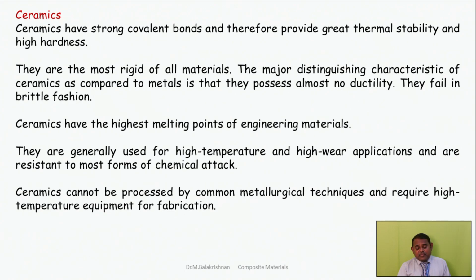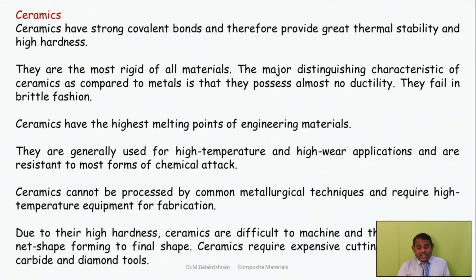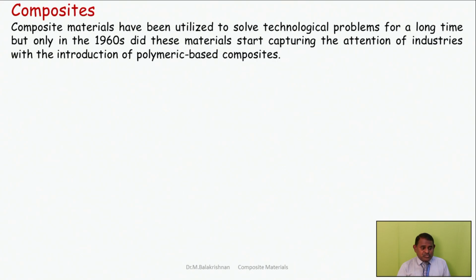And ceramics cannot be produced by common metallurgical techniques, and they require high temperature equipment for fabrication. Due to their high hardness, ceramics are difficult to machine and therefore require net shape forming, or final shape production. And ceramics require expensive cutting tools such as carbide or diamond tools.